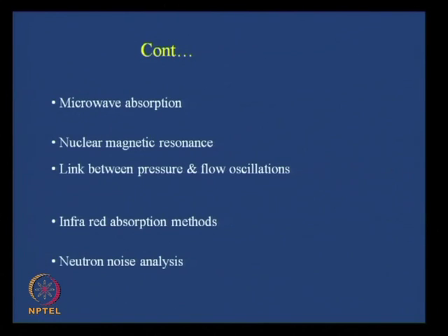Now, what is the beauty of this technique? Most of the techniques I have told you are very good for water continuous systems or liquid continuous systems. For high quality flows, most of them do not work well, because the absorption or the attenuation of radiations is maximum for water and much less for air. So, when there is a large amount of air, whatever small water amount is there does not much affect the attenuation process.